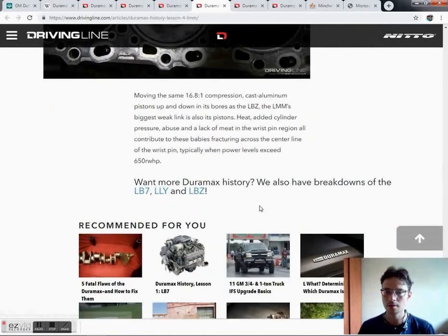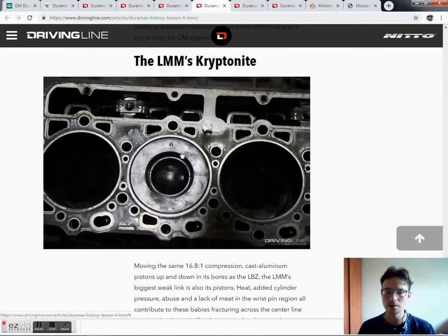As you can see, it has the ball and piston combustion chamber. If the bore is 133 millimeters, the combustion chamber diameter is maybe 60 to 70 millimeters.